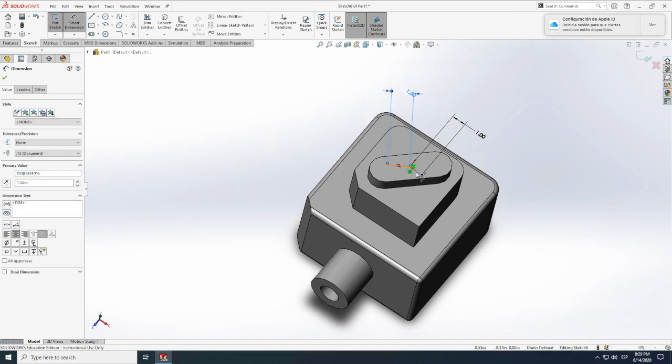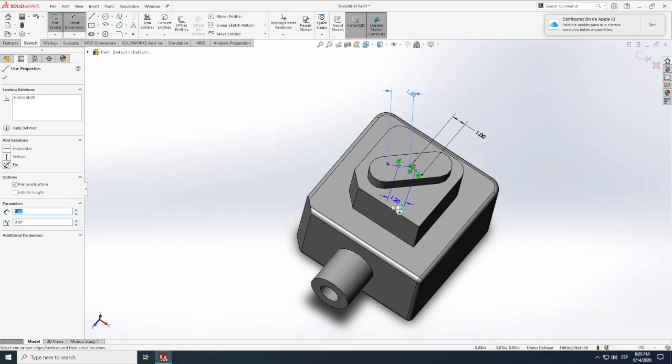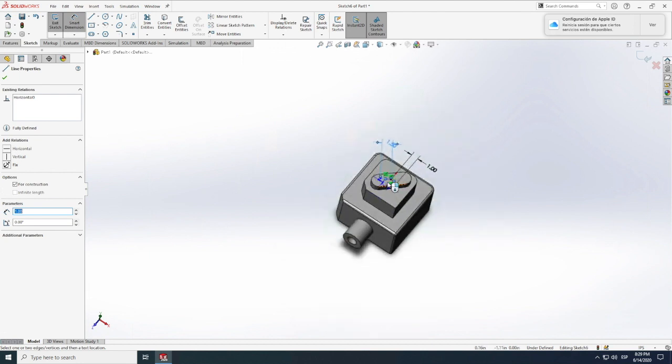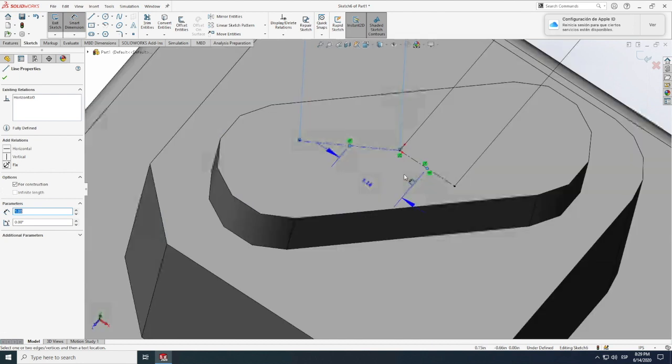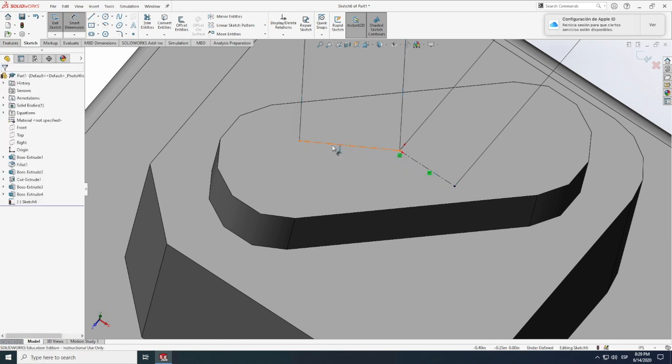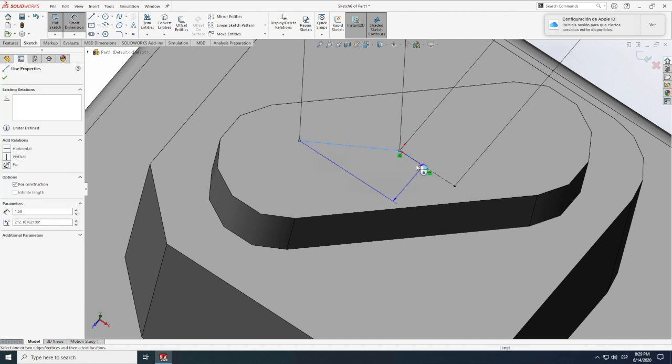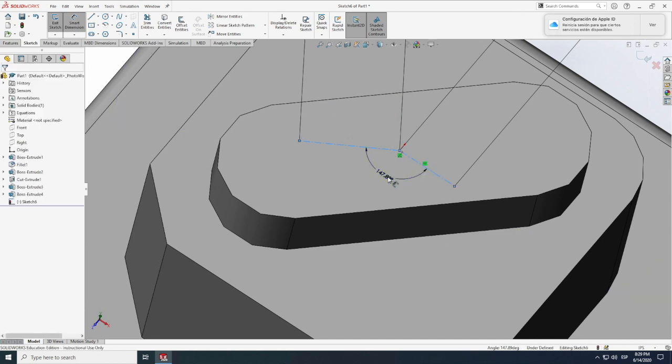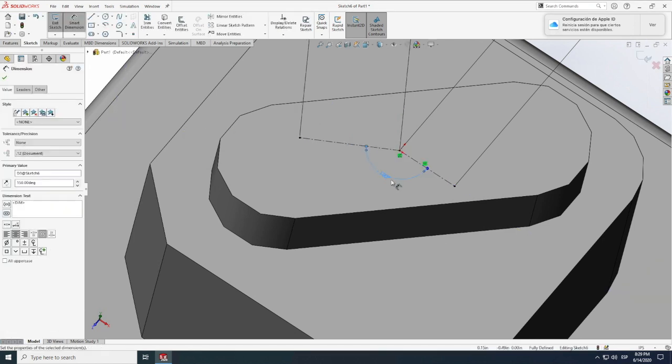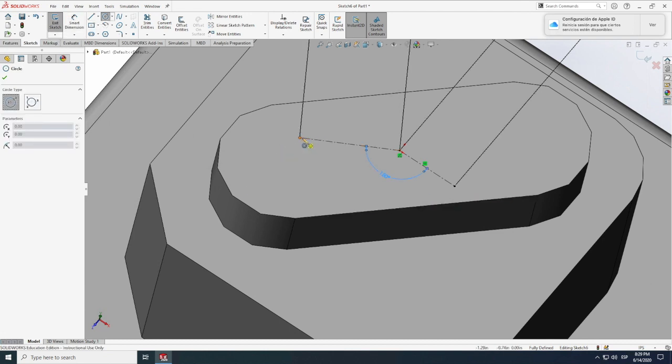Because now what we can do is click over there and define, oh, it's not working yet, because I want to define the angle between there, because let's suppose we've been told that that point has to be at some particular angle from there, at that distance. So we can definitely do that. Oh, there we go. Let's say 150 degrees. There we go, beautiful. And then we can draw a quick circle over there.